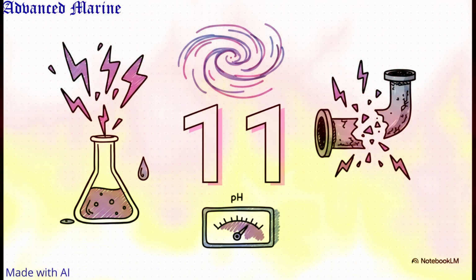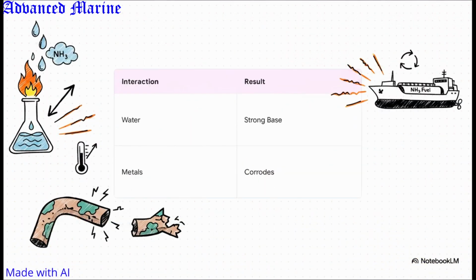This creates a highly corrosive, strong alkaline threat that will easily eat right through standard industrial materials, plus it becomes an alkaline-reducing agent, meaning it reacts dangerously with things like chlorine, fluorine, bromine, mercury, and hypochlorite. That number, 11, is the primary reason why your standard plumbing and storage solutions are completely off the table. This perfectly illustrates the varying threat levels.